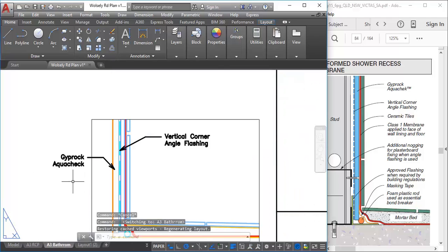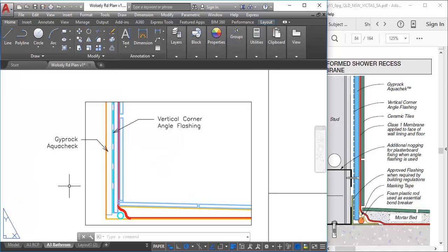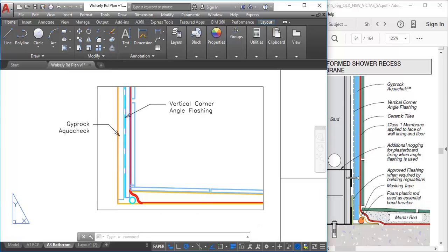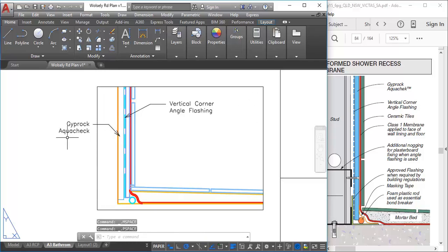When they're on the sheet, it's a little bit harder because to copy the viewport and the objects together, well, it works, but it doesn't always give you what you want, because then you'll need to adjust the viewport. And if that doesn't make sense to you, then just try it and you'll see what I mean. But again, you'll see before long that you will sometimes need to do notes in model space, like I did the first one. And here you can see I can't select this second one because that was done in paper space, and again there'll be times when you need to do notes that way on the page, or again, paper space.